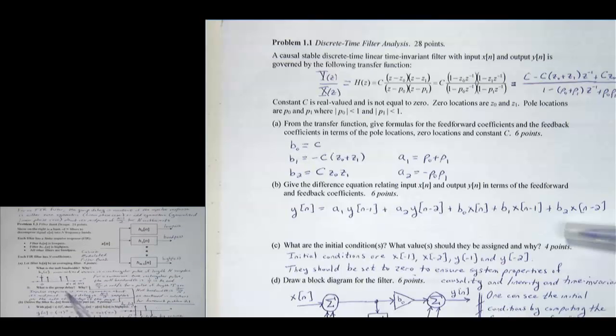And so in this case, for the averaging filter, which again, we did the 2-tap case in lecture, this has even symmetry about the midpoint in the impulse response. And that means that our group delay is going to be constant, N minus 1 over 2.